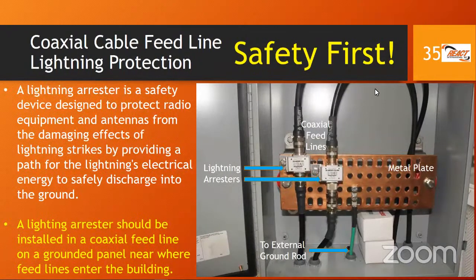So that is essentially describing this. Apart from grounding our radios, antenna tuner, and power supply to a ground bar, apart from grounding our tower, as we saw a slide ago, we are also grounding our feed line or coaxial cable, because that's another part. It's copper inside of there. Should the antenna be struck, it could come into our house and affect our equipment, or if we are nearby, not good at all.